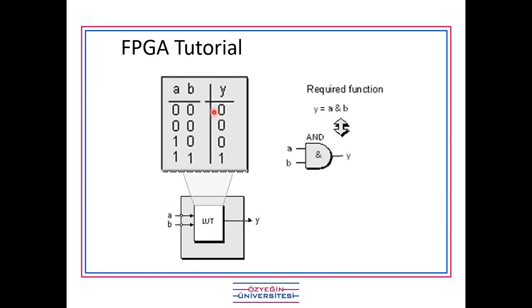So the LUT is saved inside, yes, this is the table, a truth table, by the way. It's a truth table. So this truth table is saved inside the LUT part. So whenever input comes, I get the output immediately. Okay. So in this format, we can put any designs, any combinational circuits or any sequential circuit that we have, and describe them with our code.